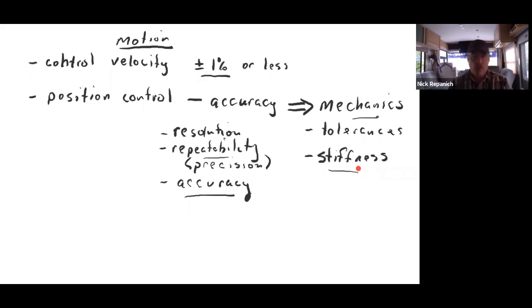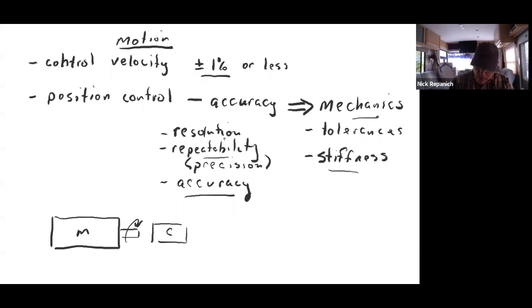Okay, so motion control, we're trying to control position of something. And in reality, what you have to remember is that you're going to have some sort of motor at one end, and the motor's spinning, and chances are you're going to have some things in between, maybe a coupler. You may have some gearing, right? And now you're coming off of this shaft. You may have a ball screw out here. So finally out here, you have the mass that you're trying to move.